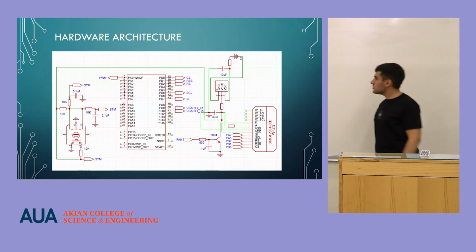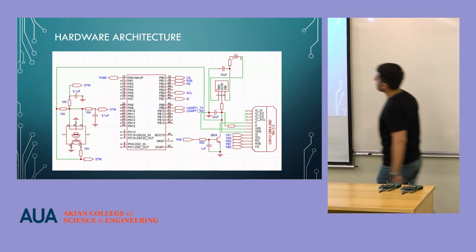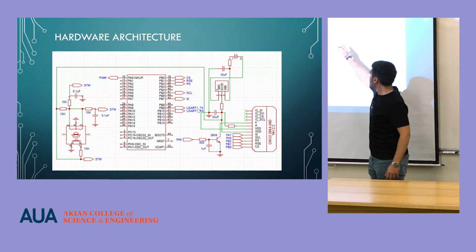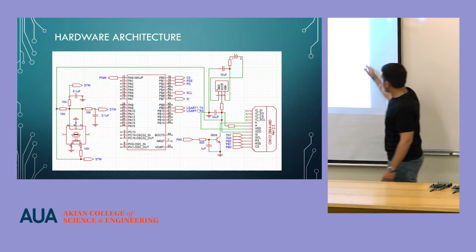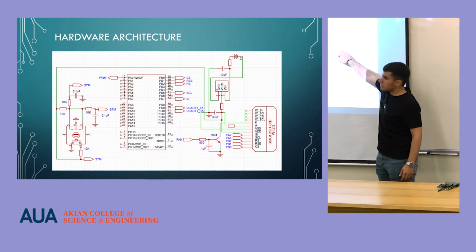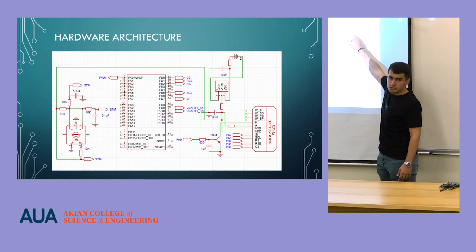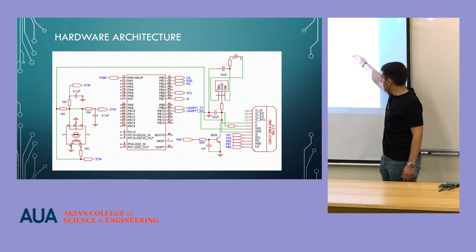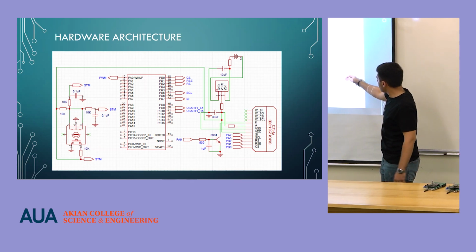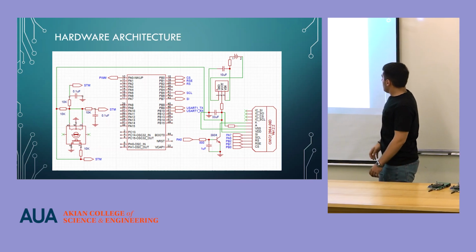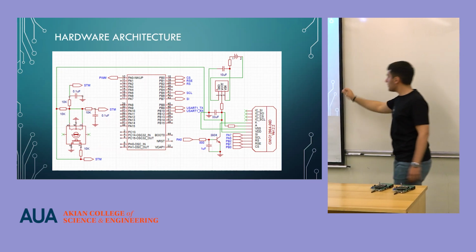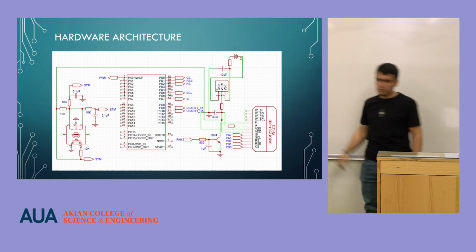Here is the circuitry that I've created. This is the STM32 microcontroller and the pin configurations. This is the LCD that I'm using with its pin configurations. This is the power source. This is the LDO, which converts 8 volts to 3.3 volts to supply the voltage for the PCB and the display. And this is used for PWM generation to regulate the backlight brightness of the LCD.